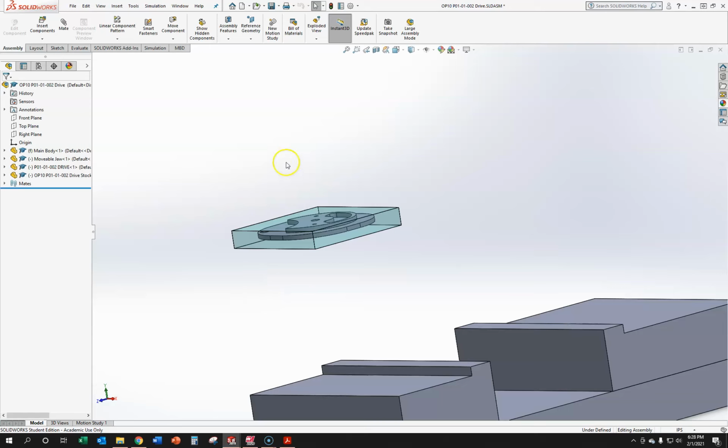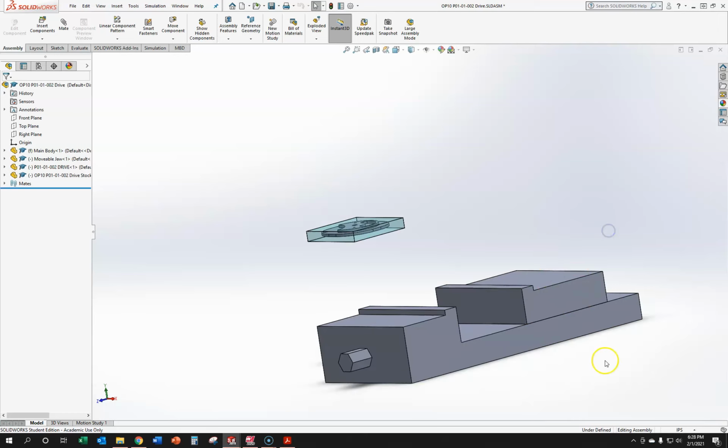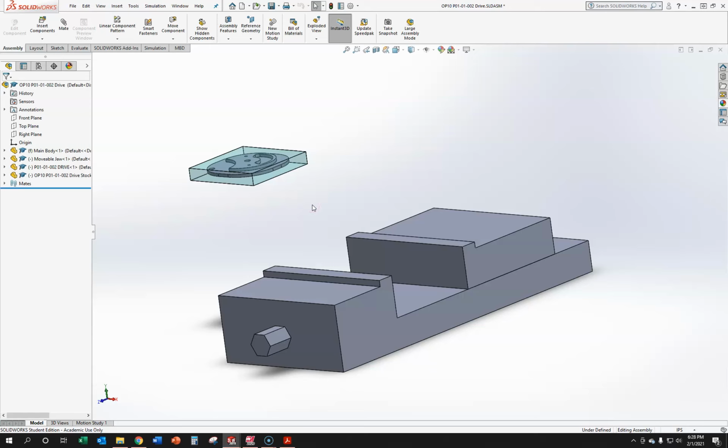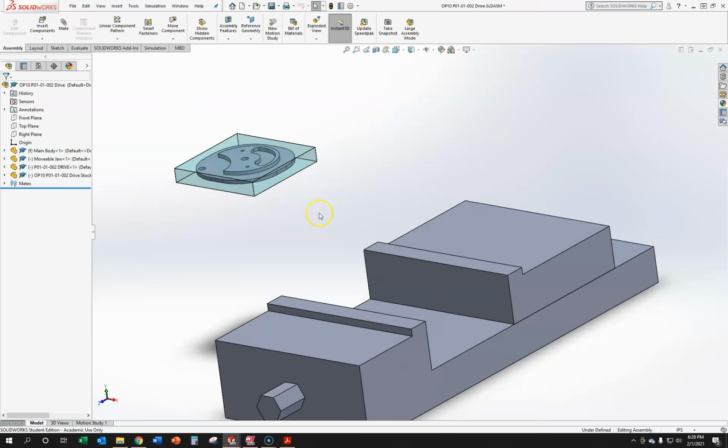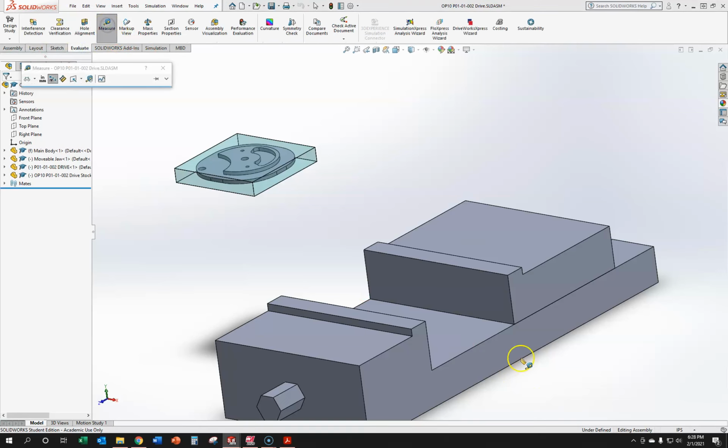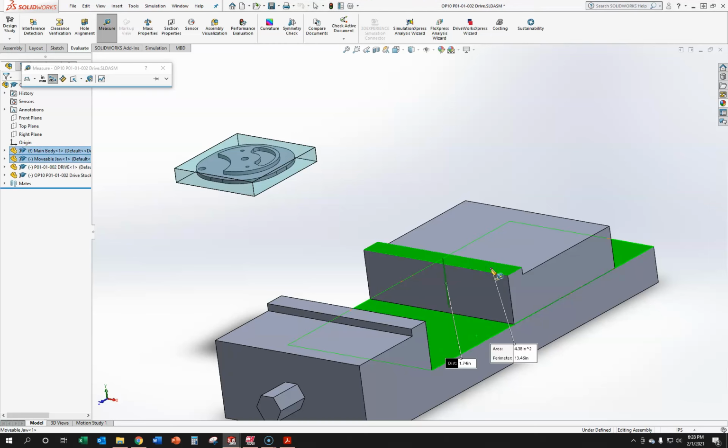So this has to be lifted up a little bit. We can probably just do the math on that. And again, we can double check our dimensions here. We already have 1.5 inch parallels made. I believe that's probably what we're going to want to have. That means we're going to have 100 thousandths of material sticking in the vise, which isn't terrible. You wouldn't want to really rip material off of this like that, but 100 thousandths, not terrible.